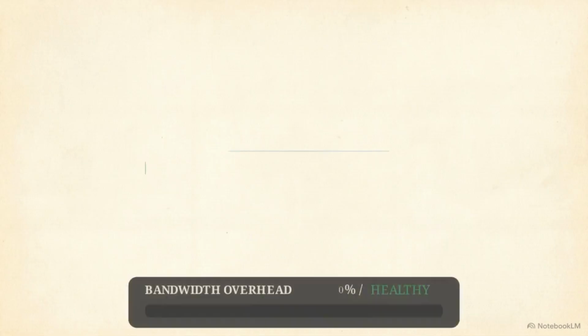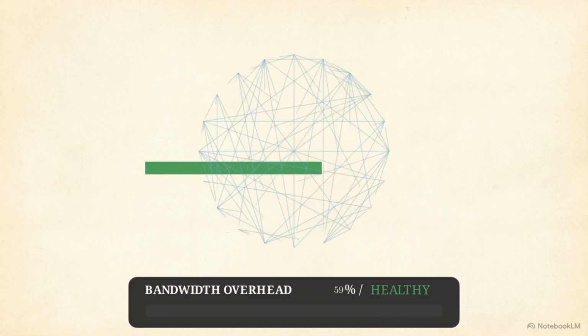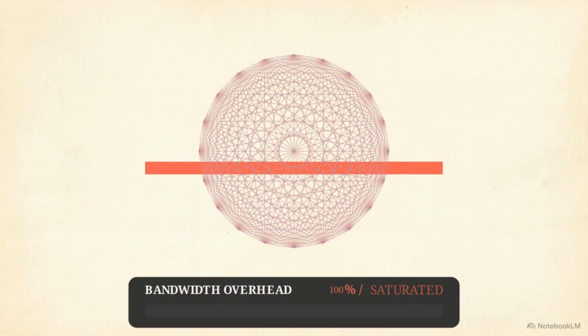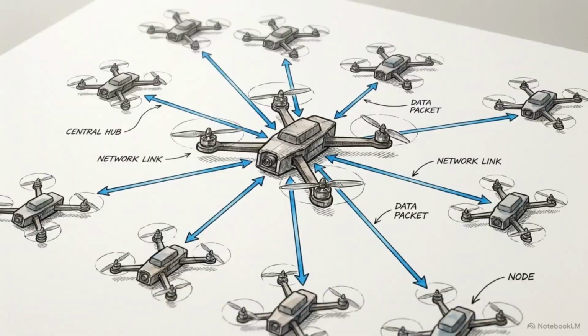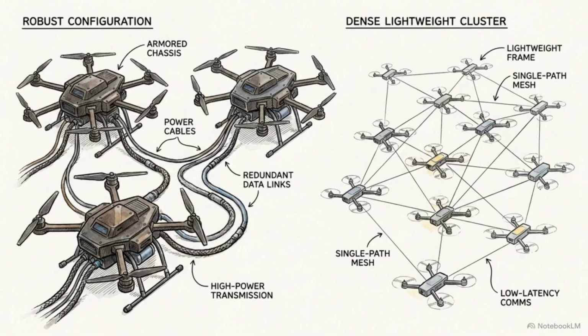However, this topology has a scalability bottleneck. Packet overhead increases exponentially as drones are added. A swarm of 20 drones would generate an overwhelming web of signals that saturates the available bandwidth. Supporting larger fleets requires an alternative topology: time difference of arrival. Time difference of arrival requires fewer packets, providing high scalability, but it trades efficiency for a strict requirement: all nodes must maintain perfect clock synchronization. Designing a swarm requires calculating the trade-off between unsynchronized reliability and synchronized efficiency based on the network size.